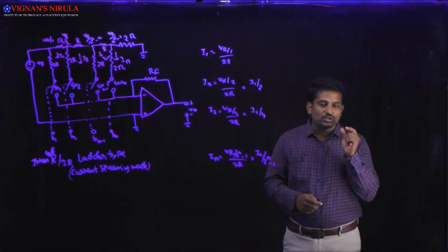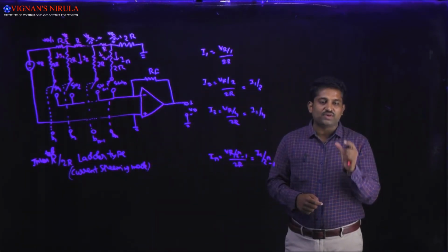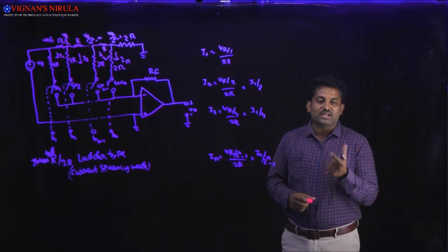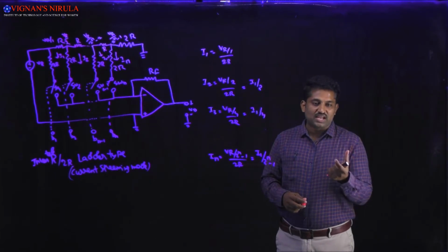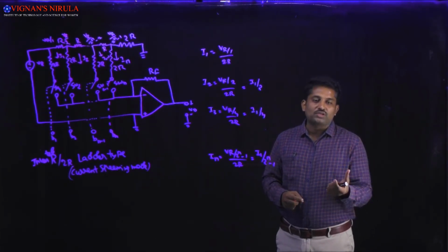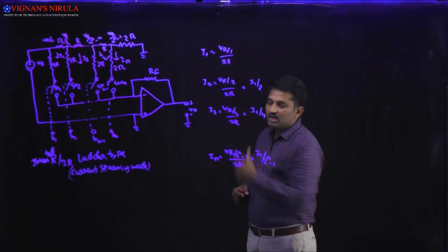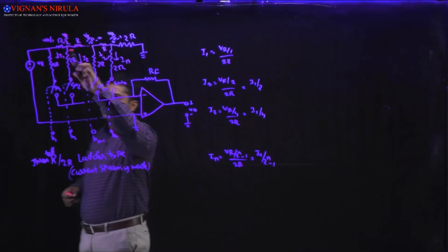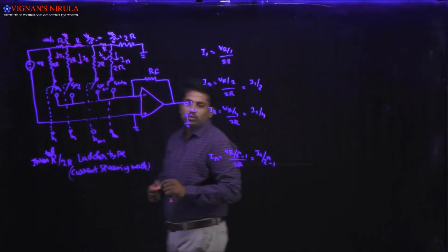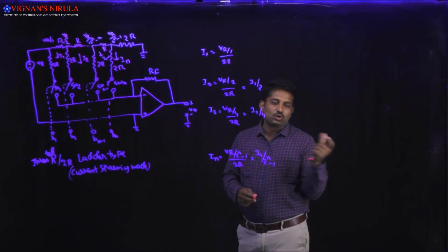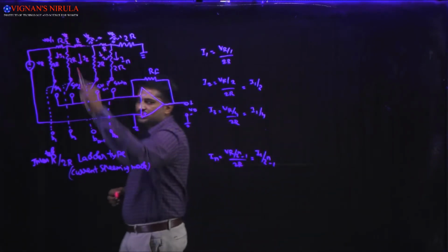And one more thing you have to observe in this inverted R by 2R ladder type DAC technique is, for generating the voltage scaling we require a series resistance to generate the voltage drop across the two nodes. That's why here we are connecting a resistance R between the two nodes. For generating the voltage scaling at the nodes, we are using the resistance R.